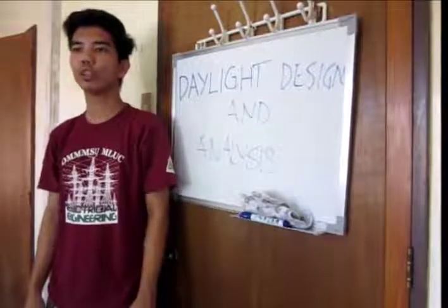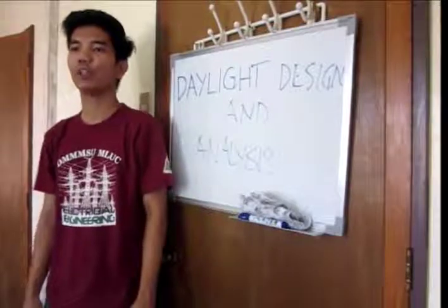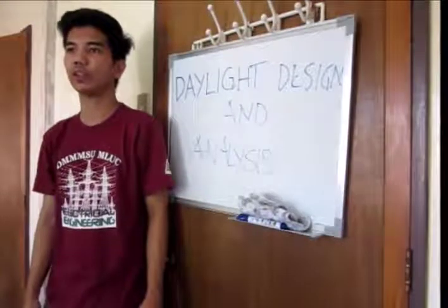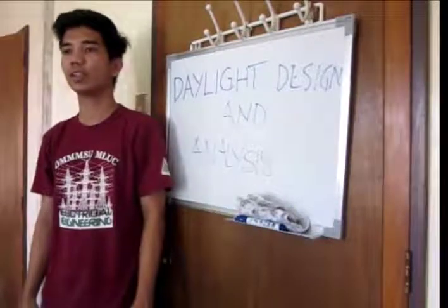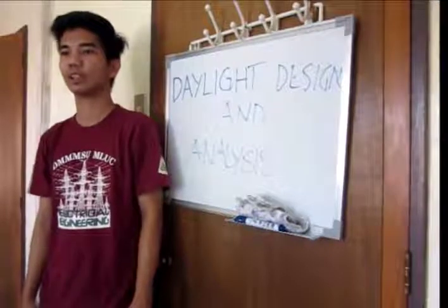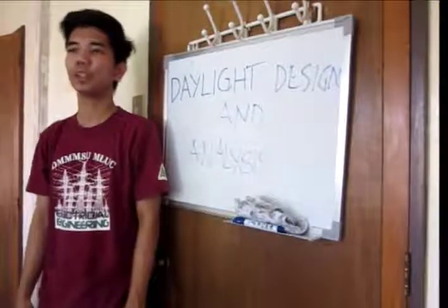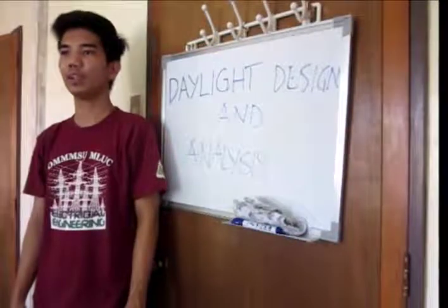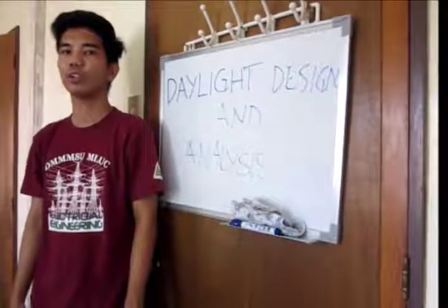How to control the daylight? A range of methods are available to control the amount of daylight that penetrates into the building: the fixed internal, fixed external, and variable external. What is fixed external? Fixed external permanently obstructs skylight and is maintenance free but is architecturally dominating.